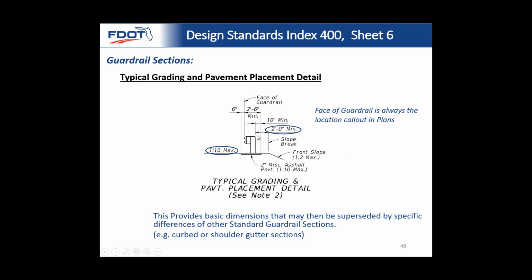And again, you have your 2 foot minimum to that slope break. So if you use a deep post, the slope break would be here. That's a very unique case. In general, it breaks 2 feet behind, and you have plenty of soil around here to resist the rotation of the post.